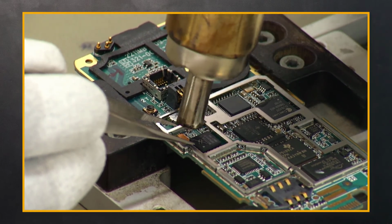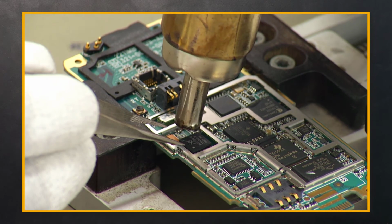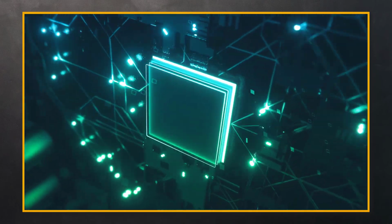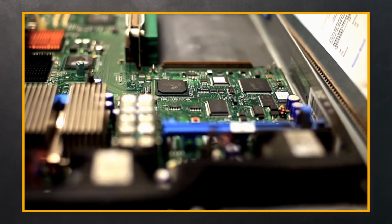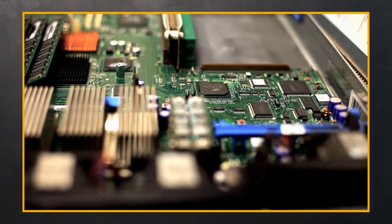A ball grid array is a type of surface mount packaging used in the semiconductor industry. It has a grid of solder balls that form a permanent connection between the die and the package. It establishes an electrical connection between the two parts and is therefore subject to thermal stresses and thermal fatigue. Due to these reasons, structural and thermal analysis of ball grid arrays is of great interest in the semiconductor industry.